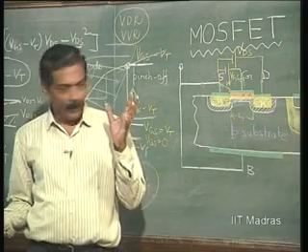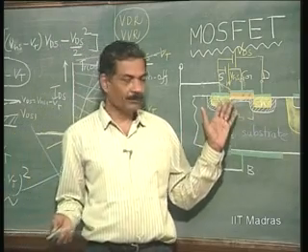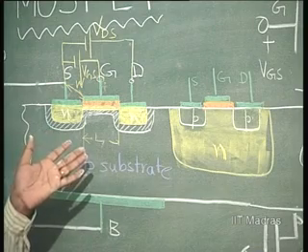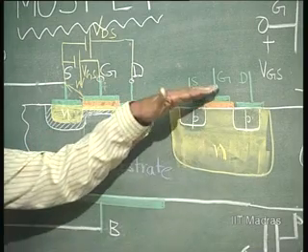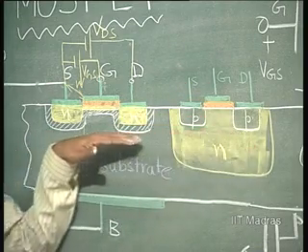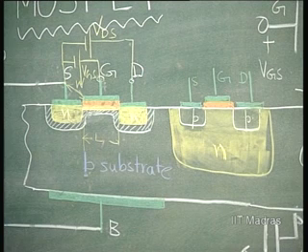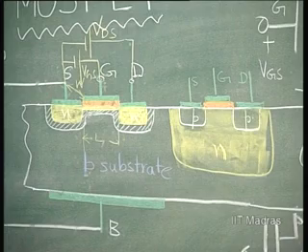The advantage, of course, in the previous ones of N-channel or P-channel is that the number of steps is less. Here the number of fabrication steps is more. The more the number of steps, the less reliable the system becomes. The more the number of times human beings interfere, the less reliable the system becomes. This is always the general truth in any system.